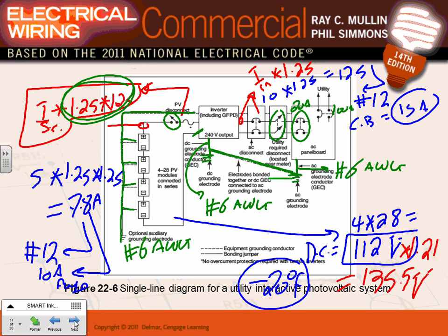Any comments, guys? Any question about the voltage rating of the system? This is DC, by the way, on the DC side. How do you size the DC? 1.25 times 1.25 short circuit. And the voltage that they use here is called V open circuit, the open circuit voltage. What's an open circuit voltage? You have a panel and you measure without any load across the panel. You just measure the voltage. That's called open circuit, and the highest is the open circuit.